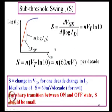It is actually the inverse slope, that is delta V_GS by delta log I_D. So, subthreshold swing or subthreshold slope is n into V_T log 10, and V_T log 10 is 26 millivolts into log 10, that is about 60 millivolts. So, subthreshold swing is 60 millivolts into n. What does it mean? Delta of log I_D is equal to 1.